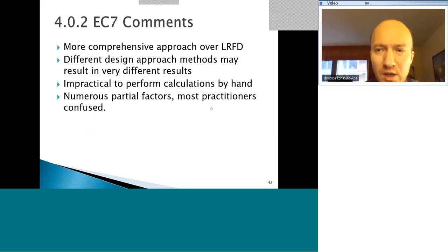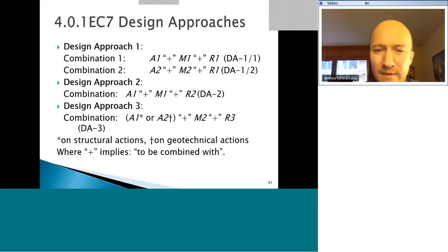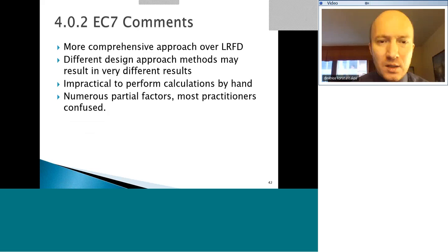There are different methods. One of the things that I want to say here, for me not to skip this, is that it's not necessarily that you're going to be adding this directly. The Eurocode allows you to amplify the effect. So you could actually, in theory, run an equivalent analysis, and we'll see how that can happen.